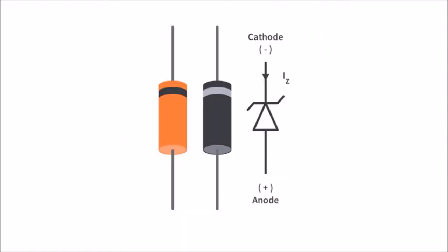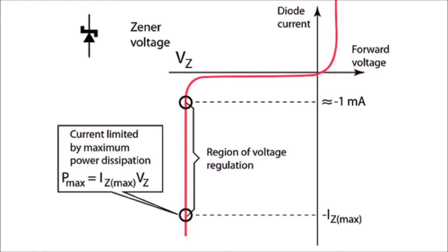The Zener diodes are manufactured with great variety of Zener voltages, and some are even variable. Some Zener diodes have a sharp, highly doped p-n junction with a low Zener voltage, in which case the reverse conduction occurs due to the electron quantum tunneling in the short space between p and n region. This is known as Zener effect.